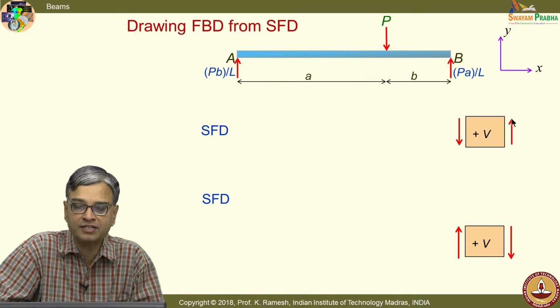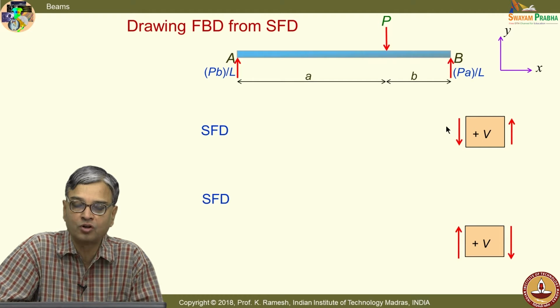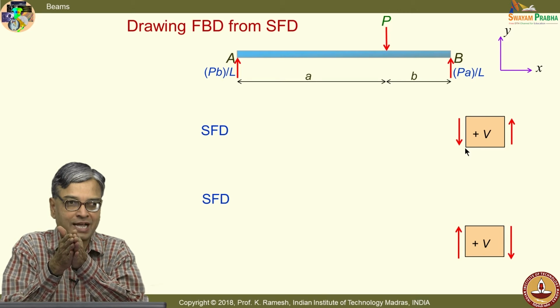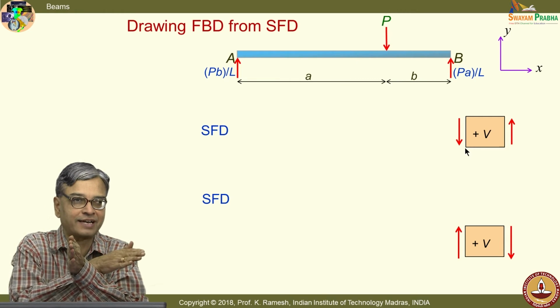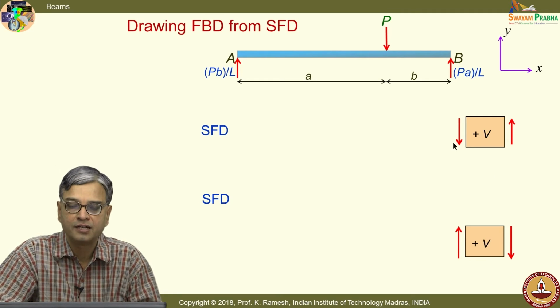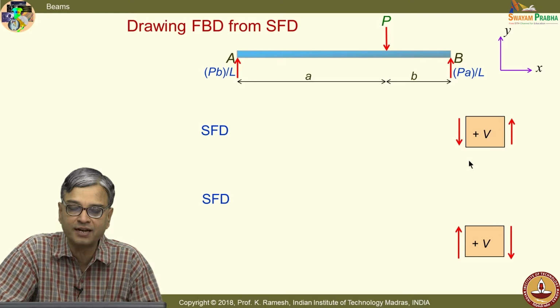And you should recognize when I write the sign convention like this, it is not a block. What it says is, what is the sign convention I should use on the positive surface and what is the sign convention I should use on a negative surface. You have to imagine that this is collapsed as one plane. I look at the positive side, I look at the negative side. For convenience, we put it as a block. It is a block of 0 length, you can take it. So, what I would write on the positive face and what I would write on the negative face.